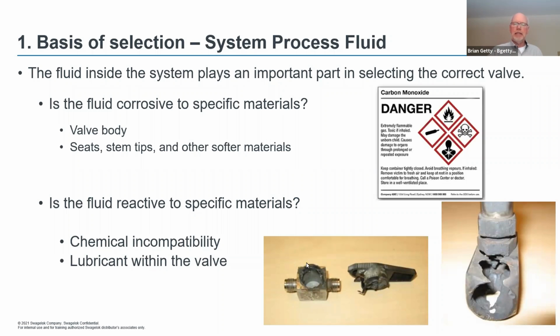But you can see in this case, the technician had installed, or whoever it was that selected the valve, had selected a ball valve. It's the question of the application: the valve and the system media were not compatible. Okay, so in this case, as you can see, this is what was left of the valve. This is what we were able to find of the valve after the explosion. The center of the valve was completely gone. So this is something to keep in mind.